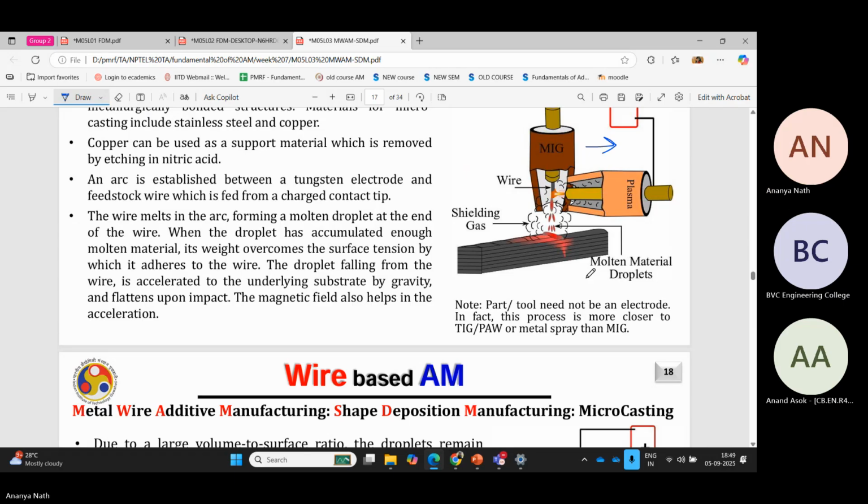Because in fused deposition modeling, there was this concept called bead ironing, if you remember. There was this concept called bead bonding and spreading and modeling. These were possible because your heat is inside the material extrusion. So you can print the metal semi-melted, semi-liquid wire, whatever way you want to print. But here you have to establish the arc.